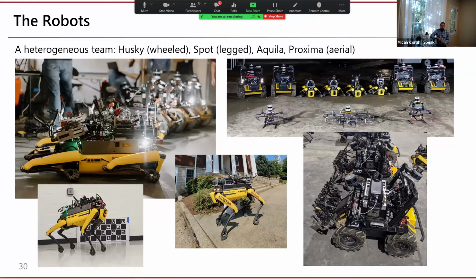These robots were equipped with extensive sensor payloads, including LiDAR, RGB cameras, thermal cameras, microphones, sensors for CO2 gas, and more. Additionally, the robots generally communicated with the operator via mesh networks, and many were able to drop additional radios in order to maintain connectivity deep within the competition course.